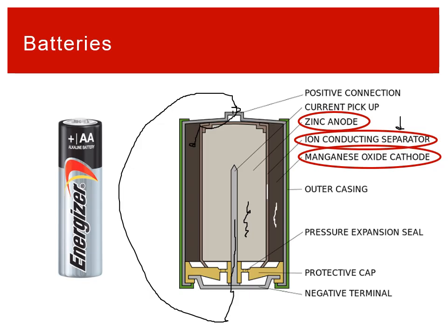So it's still from the anode to the cathode. You've just put that anode and cathode part into the same device or same casing, and they're separated by that separator. And in all honesty, the main way that batteries fail is if that separator breaks, because the whole point of the separator is to separate the anode and the cathode, so that way they can't react. The flow of electrons has to pass through the wires or whatever device is connected to your battery. If that breaks and all of a sudden they can react directly with each other, you're going to have a bad time.